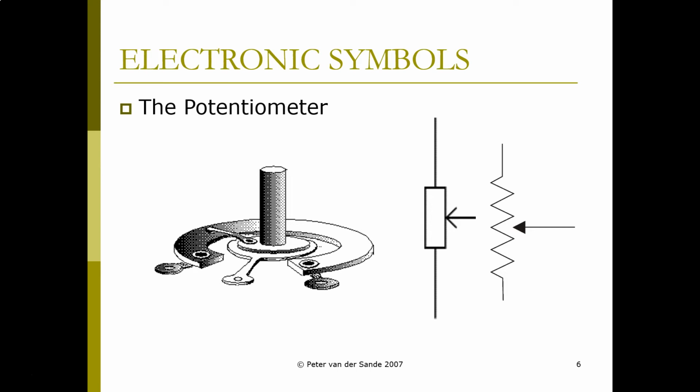Those are the two outside edges of the resistor, and the material in that circular C-shape changes resistance as you go from one side to the other. The center terminal is connected to the shaft, and then that little slider or wiper wipes from the left side to the right side as you turn the knob from the left to the right. And that's how you vary the resistance.